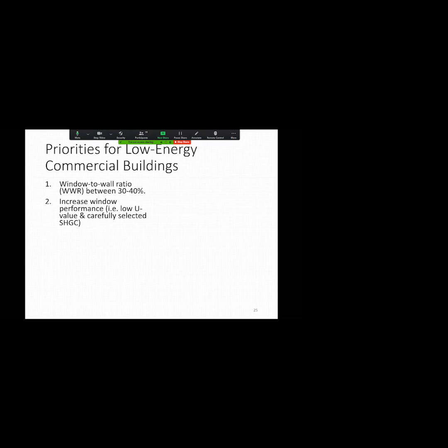So you have a southern orientation on your panels. Same thing with a building. If you want to have a passive building design and utilize some of the sun's energy coming in, you're going to have higher amounts of glazing on your southern facade to try to capture some of that sunlight coming in the winter. And then in the summer, you're going to have appropriately sized overhangs to block the sun out, to keep some of that solar heat gain out when you're trying to cool your building.